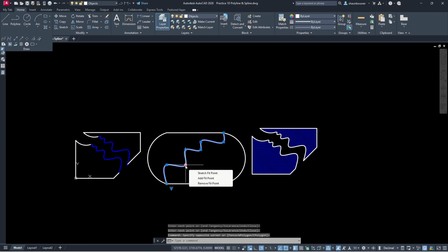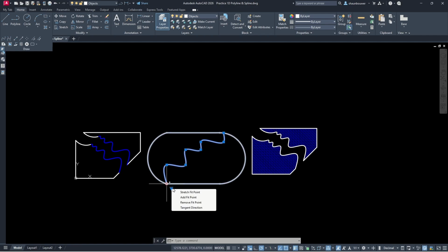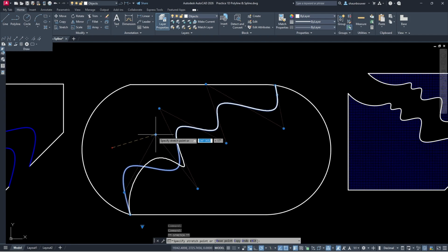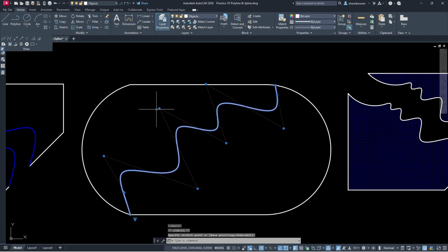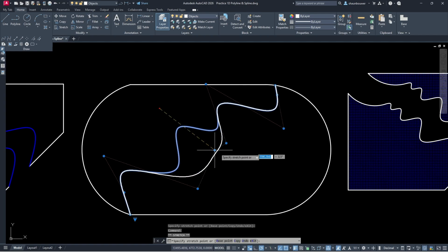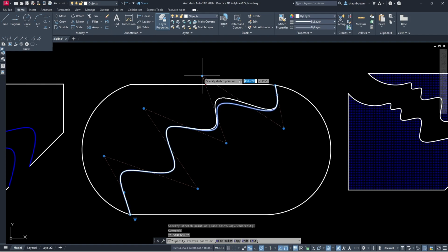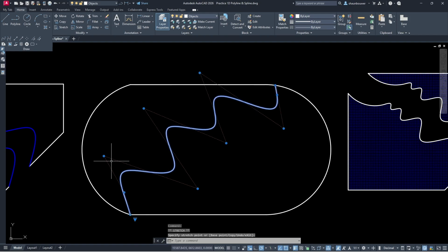When you select a spline, you will see the grips become available. You can stretch them, add additional points, or remove points. Then you can control the vertices with the drop-down arrow that is displayed at the bottom of my spline. And with these vertices, you can control the free-form shape. You can also input coordinates to this shape, or angles and length, to be more specific.